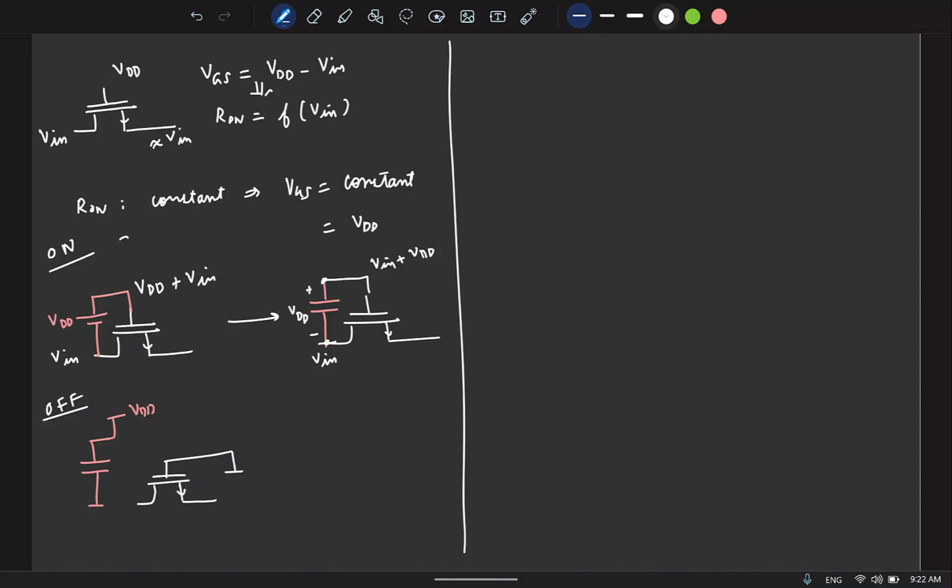So again, when the switch is on, I'll assume the control signal phi is 1. Here the control signal is 0. So this is the main switch. Now when the control signal is 0, we want the gate voltage to be pulled to ground. So what should I put here?